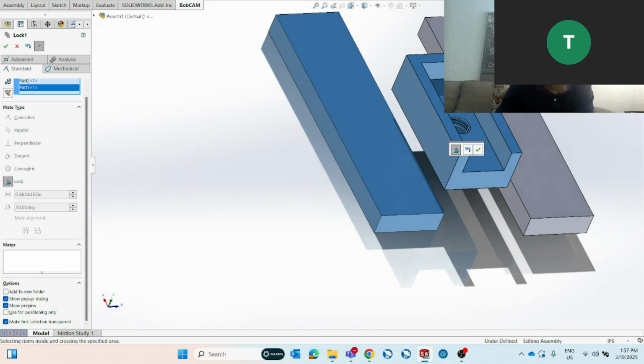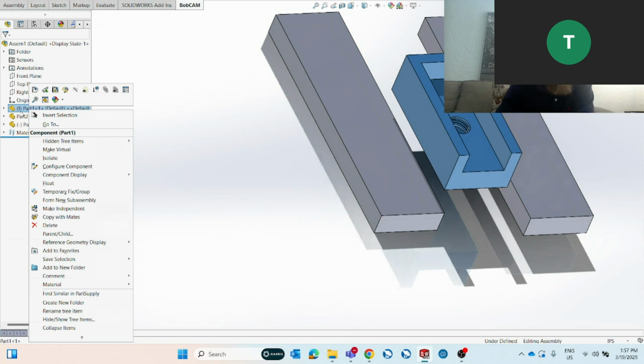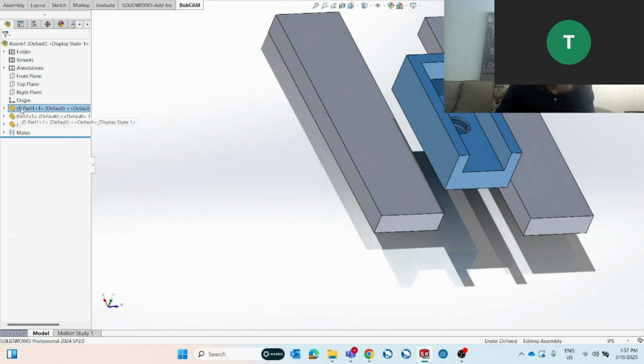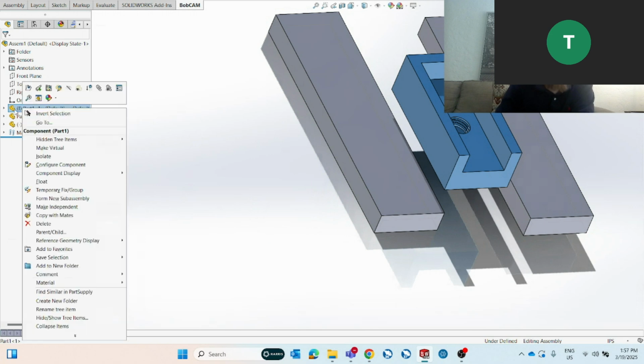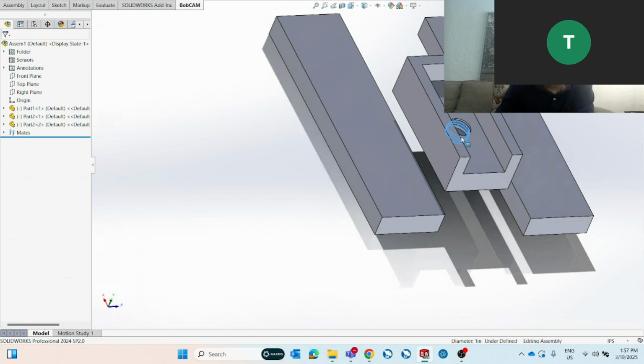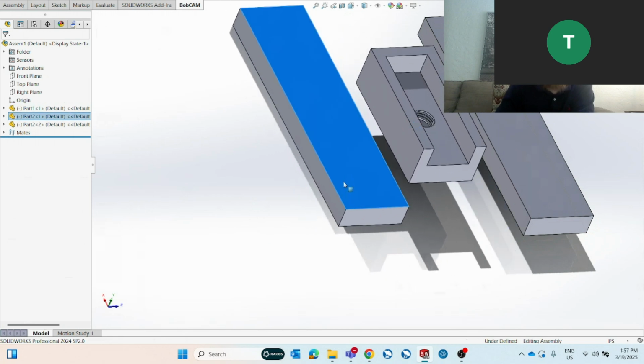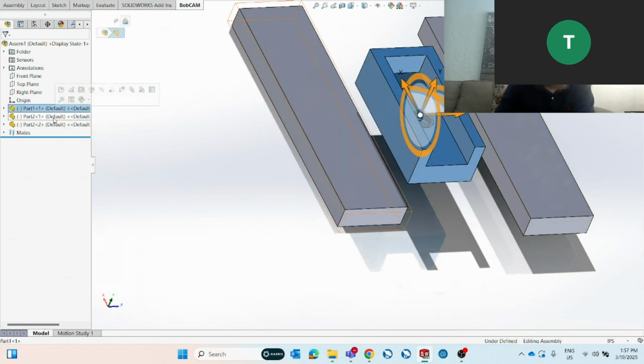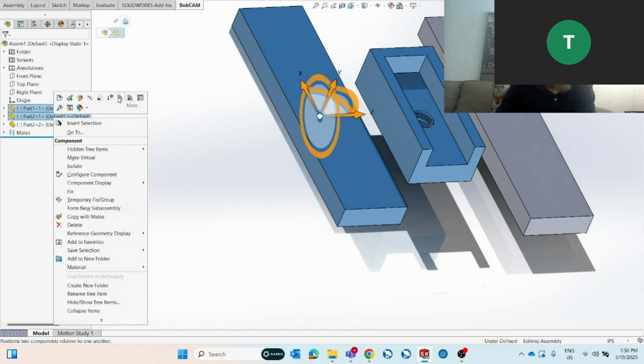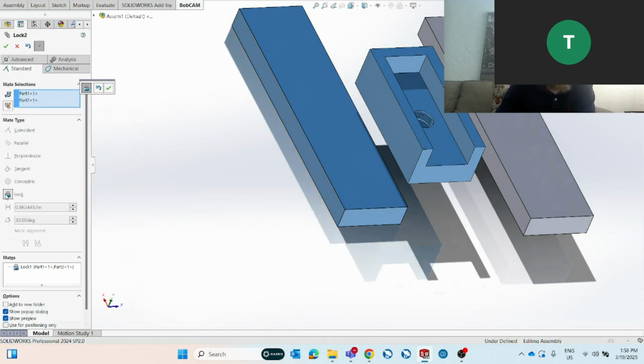Oh, I think there's one other weird one here with SolidWorks: right click on the original one. And when you see a letter next to the part in the assembly, the letter F means that it is fixed. So you can right click on it and you can change it to float so that now you can move it around, and you can also change the mate references for each of these, I believe.